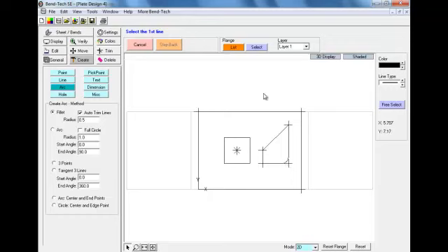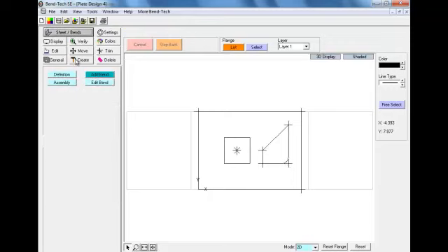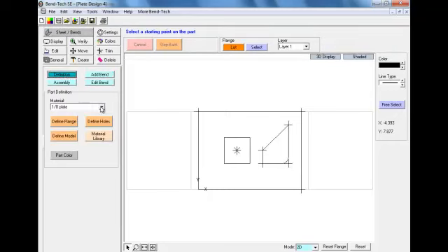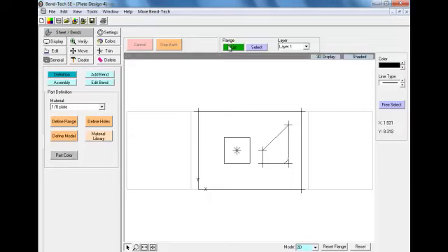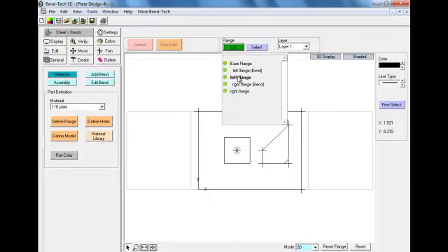Once we have both of those holes created, we need to redefine that flange. We'll do that by hitting the Sheet Bends tab, the definition button, back to plate, and define the flange. We can now create our end flanges. We're first going to select our left flange to start out.